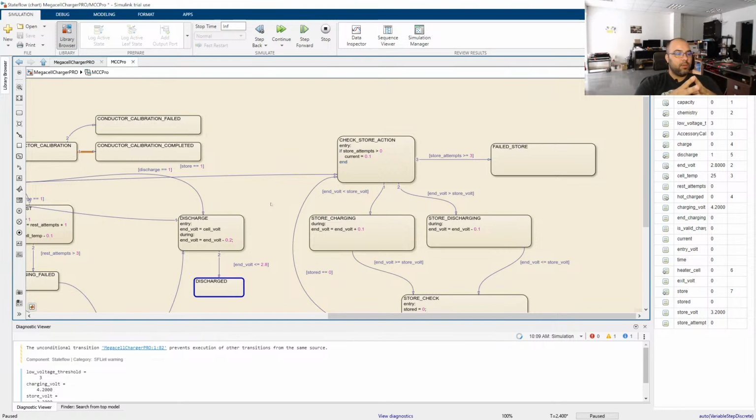And what's going to make my life easier when programming the new feature is that each cell will have its own state machine. On top of that, we're going to have a macro state machine that's going to create different scenarios, like measuring capacity, which requires charging the cell to a certain voltage, then discharging it, measuring the capacity all the way down, and then charging it.